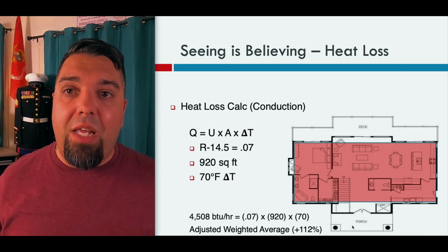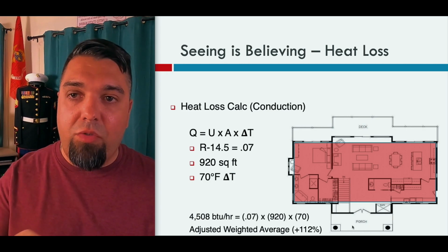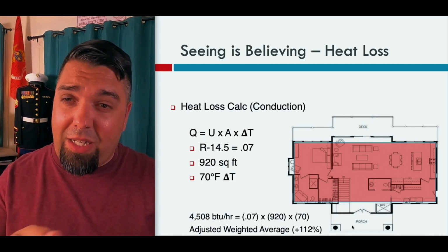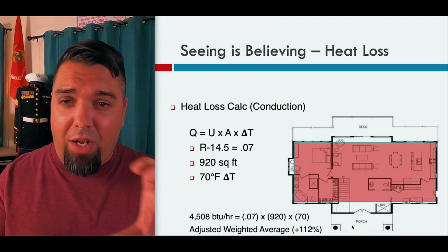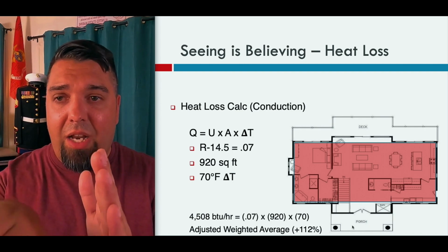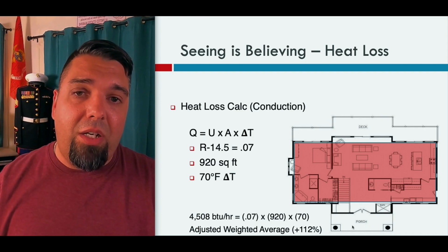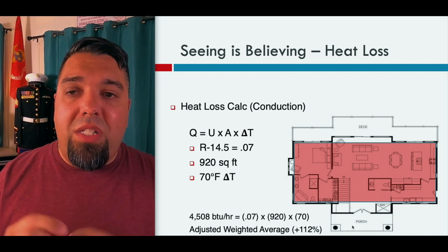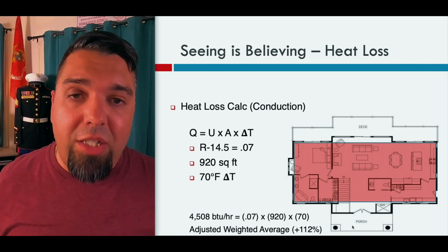You have to take a peek, let's say, with a non-conductive probe. I used to use one of the plastic knitting probes. Take an electrical outlet cover off, get my probe between the outlet and the inside of the wall to see what I have for insulation in there. See what the depth is, right? Seeing is believing, and that's how you're going to be able to trust the load calculation.